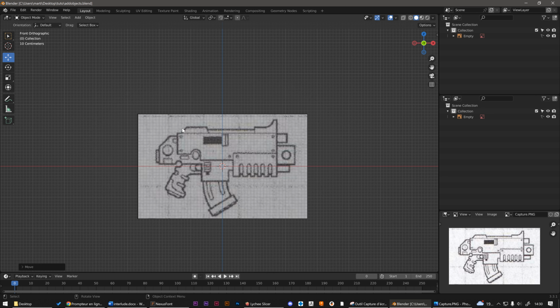Which primitive form comes closest to this element? I would say a cube, because it's a good base for anything parallelepiped. Then we will use the Scale tool to deform the cube and make it match the drawing. But as you can see, the shape we want to model can't be done with a simple cube because of this concave corner. Well, we don't yet know how to do polygonal modeling, so we will break this object down into two objects, one for the right part and a smaller one for the left part.